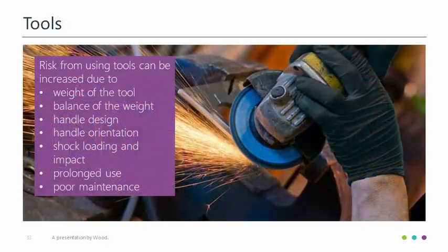Tools, and tool purchasing and maintenance in particular, are an area where there is a lot of focus in parts of Wood, especially where we are involved in maintenance work. A positive purchasing policy is in place to not only identify as far as possible low-vibration tools, but these tools are also independently tested to confirm this, colour-coded according to their vibration risks, tagged with the maximum length of recommended daily usage times, as well as their decibel noise levels.